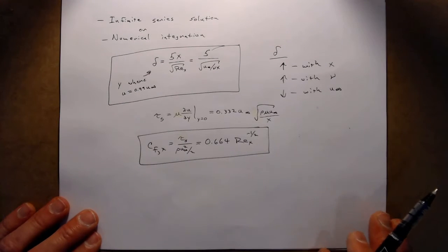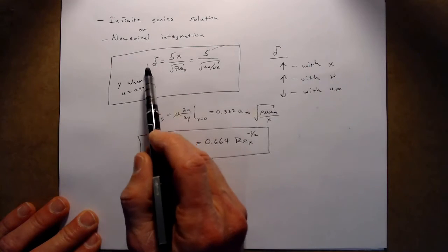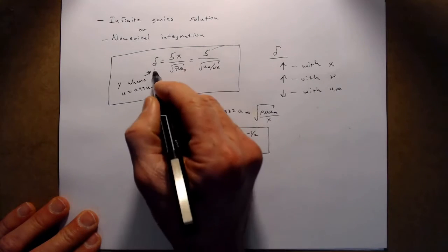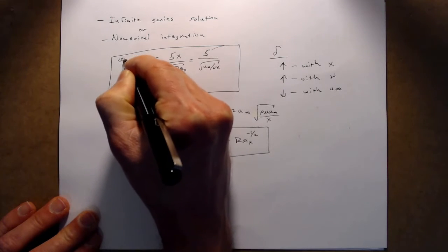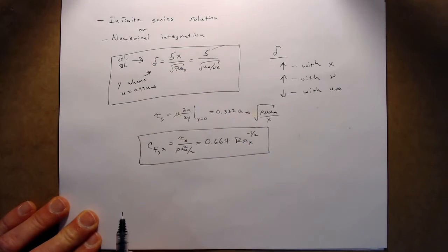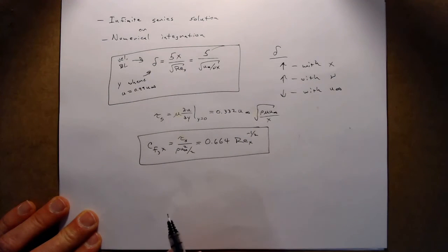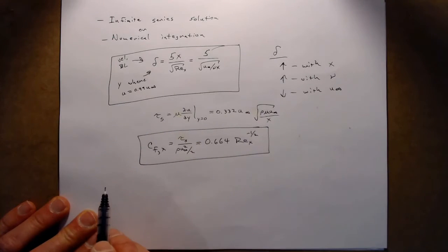And one of the important consequences is that the solution tells us something about the thickness of the boundary layer. And again, if I don't put a subscript here, I mean the velocity boundary layer. So this is the height above the surface, by definition, at which u equals 99% of u infinity.